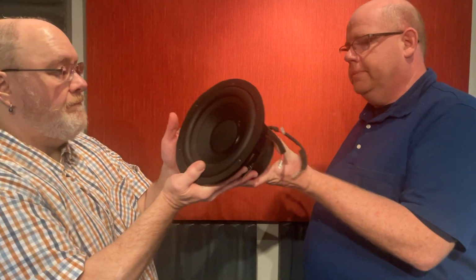But a lot of times what you'll do is, like a lot of speakers, you can run a 4-ohm woofer, say if the woofer's 80 dB efficient. Let's go with that. It puts out 80 dB with 1 watt input. Okay. And it's a 4-ohm driver. Okay. And you have a mid-range, a tweeter up here. It's a 2-way. You have a tweeter, and it's 98 dB efficient. Okay. So you need to reduce that tweeter all the way down to match this guy. Okay.